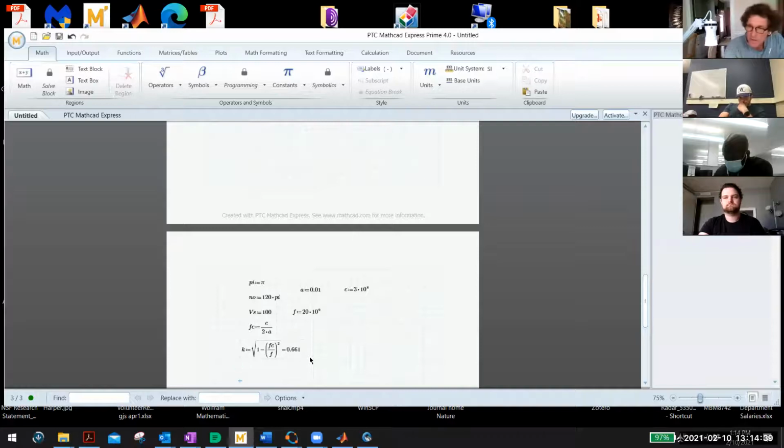You can check me on this if you get a different value, okay, guys? And that means when I take a look at this, I got A to naught there. The impedance, I'll just call it ZTE, is equal to A to naught divided by K, because it's a TE10 mode, right? That's the feed impedance that little antenna feels when it feeds it. So now I got everything.